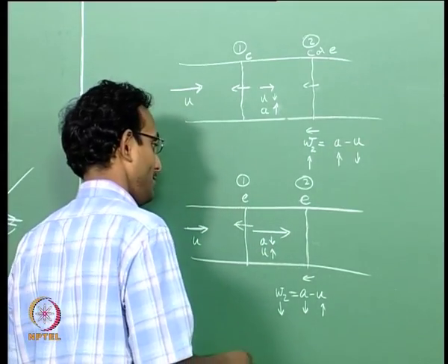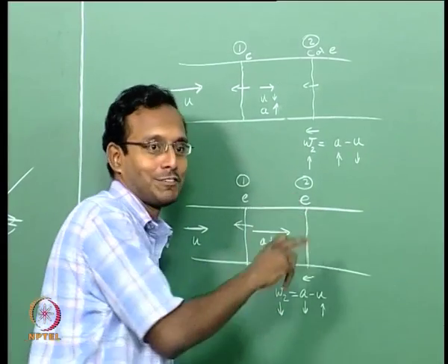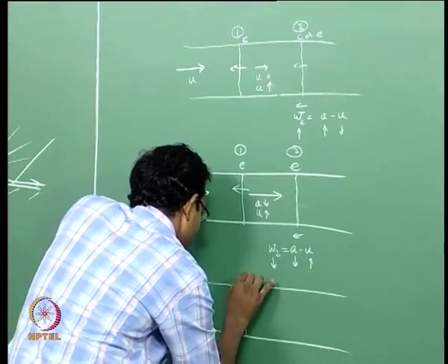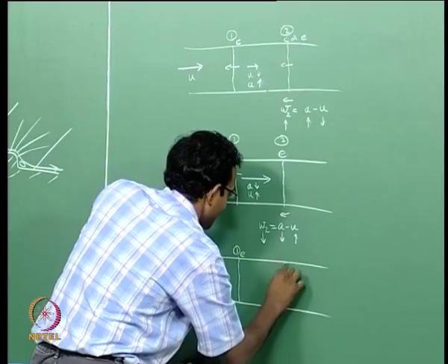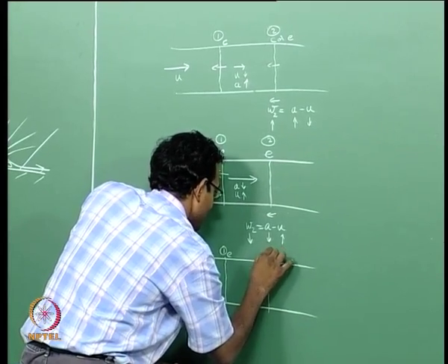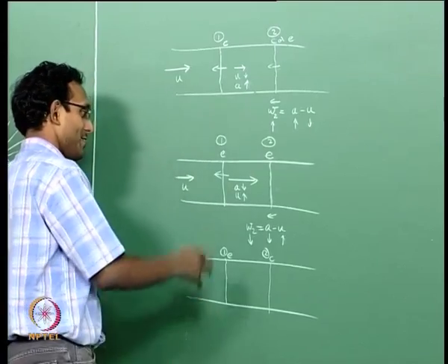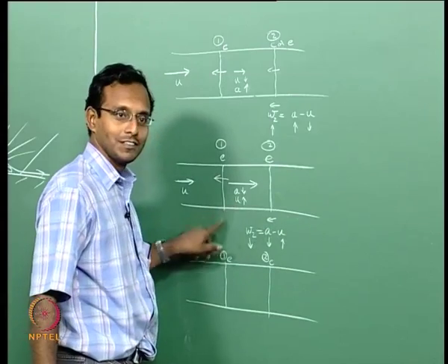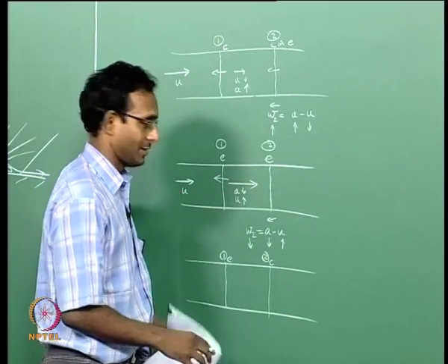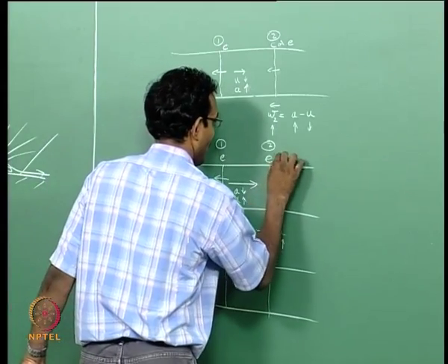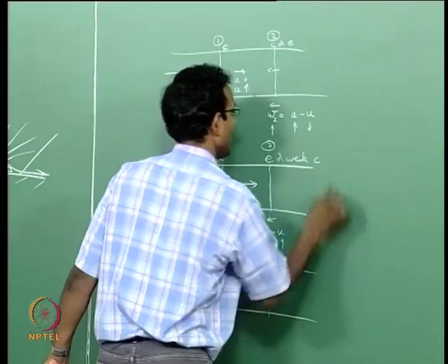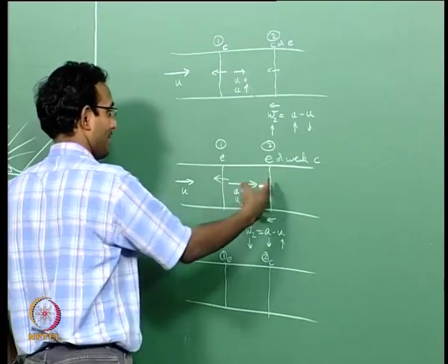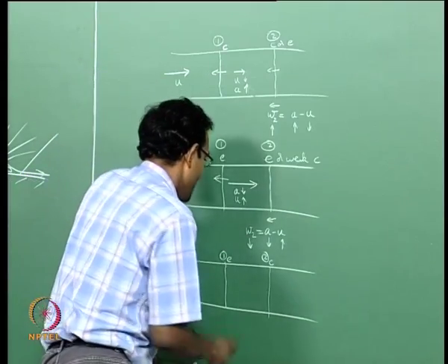Okay. Now, what happens if it is a compression wave? The second wave is a compression wave. First wave is an expansion wave, second wave is a compression wave. Okay. If I think about the same thing, if it is a very weak compression wave, it will still obey all these properties and it will behave like this. Okay. But okay, I will put that here, weak compression, it will do the same thing. Weak compression, it will follow Mach wave almost, so it is travelling with speed of sound and everything will have a similar way. If it is a strong compression,